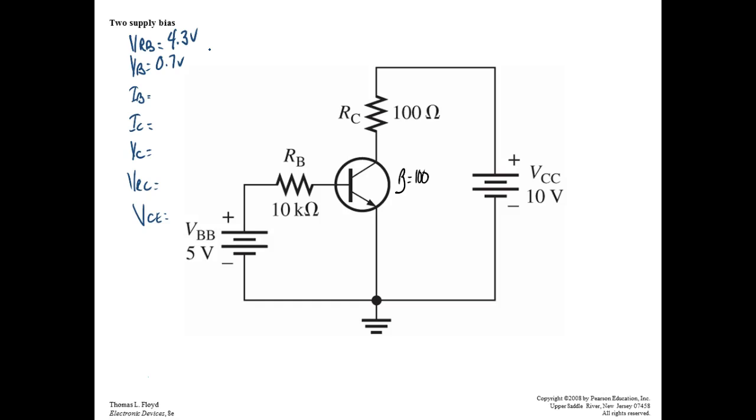You understand that? And we even did that in diode circuits. Every time we went through a forward bias diode, we took off 0.7 of a volt. We're doing the same thing here, except on a diode it was going the opposite way. On the diode we subtract the diode drop on the front end. Here the diode drop is on the rear end, right?